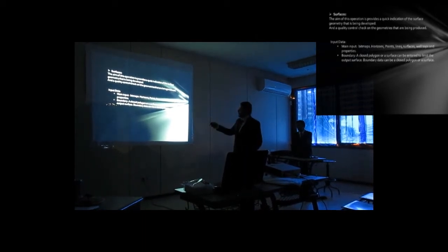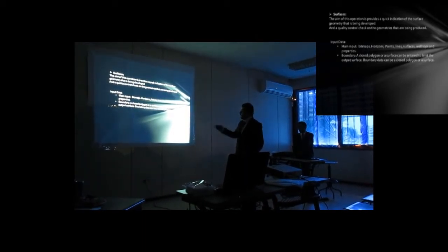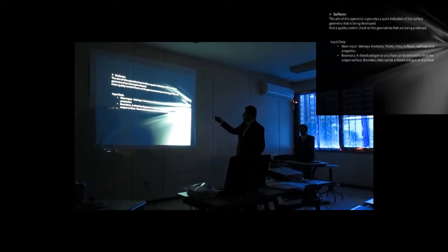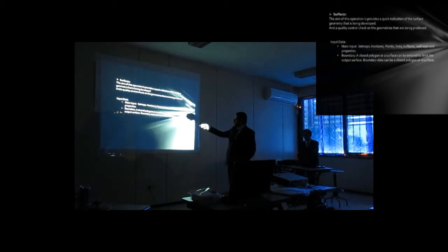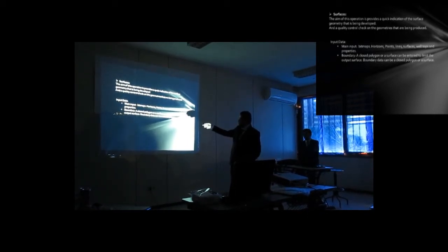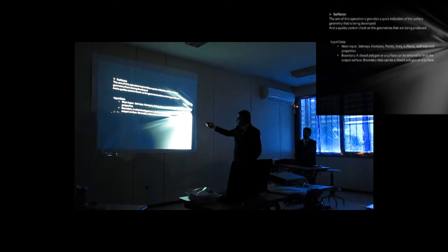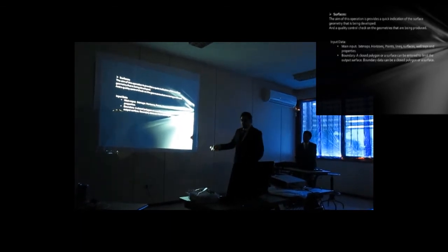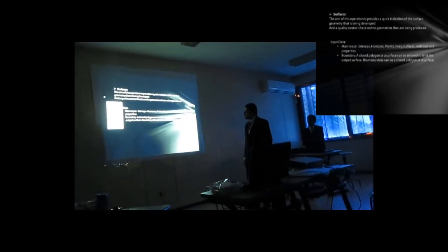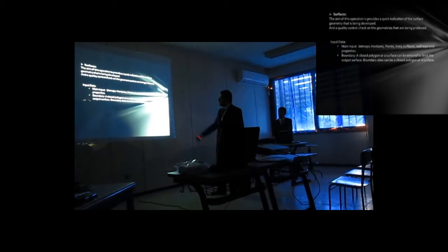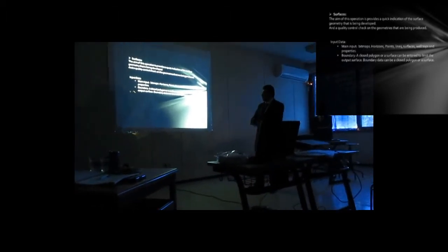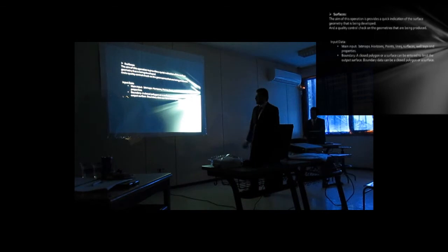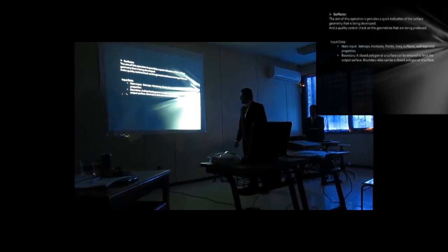The input data for creating the surfaces can be bitmaps, horizons, points, lines, surfaces, well tops, and properties. For our step here, we used horizons that have been interpreted, and we used well tops for calibrating. The boundary is a closed polygon that you create to close the area. Because if you didn't close the area, the surface will reach out of the area, and this step won't be necessary.